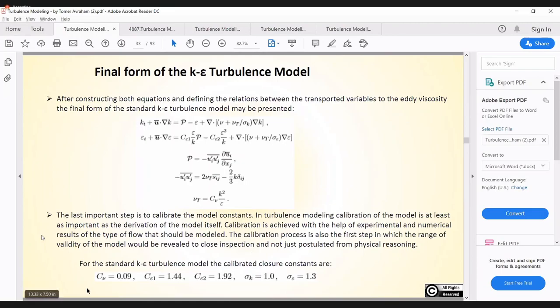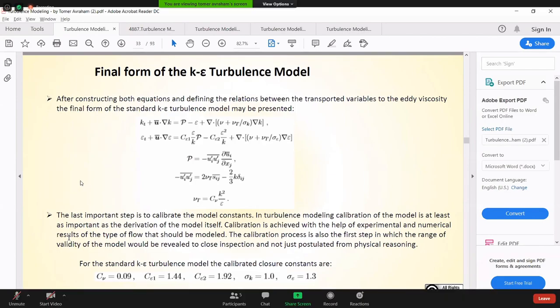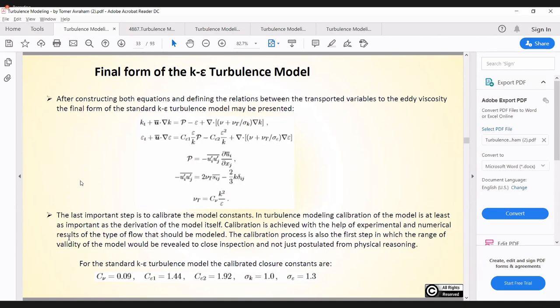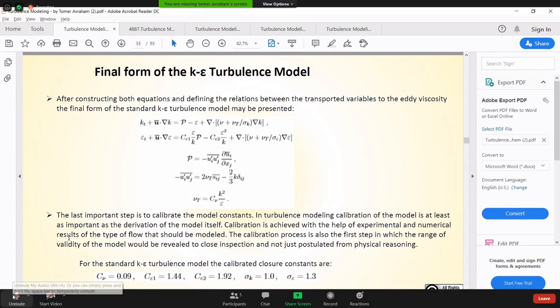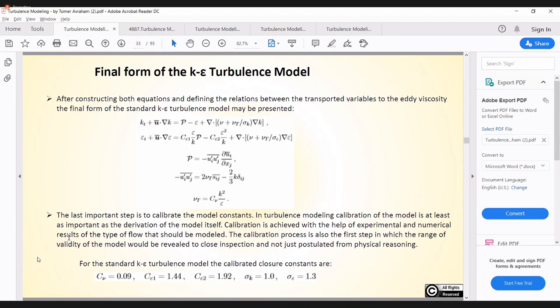I mean, we solve very complex problems of electronic systems with heat sinks, which are kind of the exact tubes that we've shown that there's no recirculation there, so we are supposed to get a mistake in the pressure drop, but then the mistake is that instead of 5 inches pressure drop, you get a half inch less.